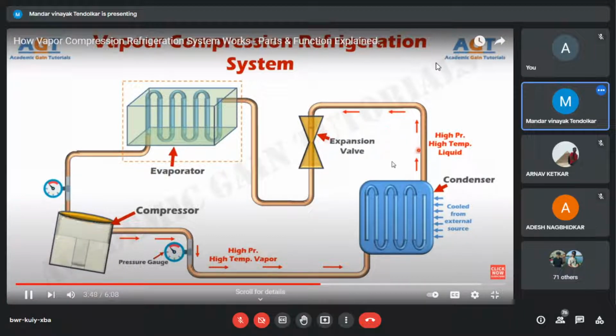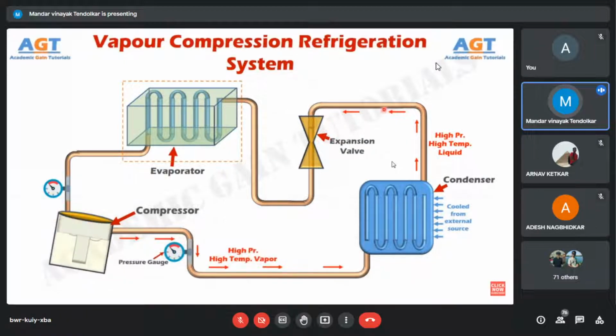Okay, fine. Refrigerant coming from the condenser will be expanded inside this expansion valve. We know that when expansion occurs, the pressure between the molecules decreases considerably, thus the temperature falls. So, this high-pressure liquid refrigerant will be expanded into low-pressure, low-temperature liquid refrigerant. In practical use, at this point we do not get only liquid refrigerant, but here we actually obtain a mixture of low-pressure, low-temperature liquid and vapor refrigerant.